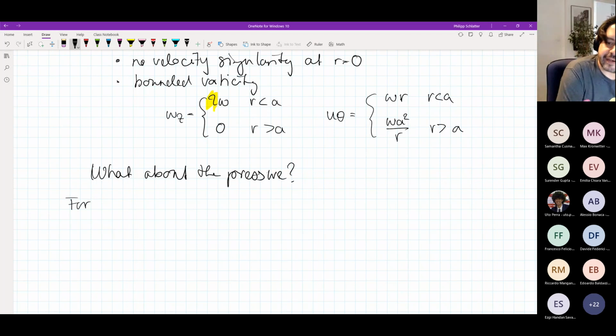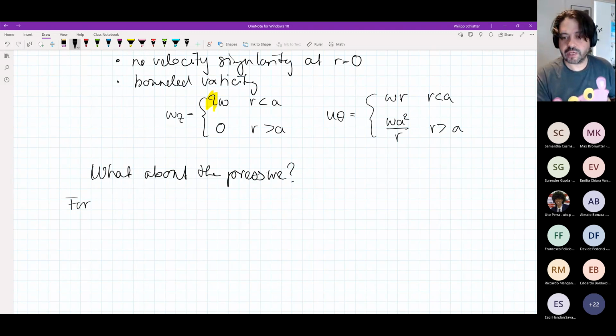Well, let's assume that the flow is inviscid, which we can do. We talked about last time that the vortex solutions are essentially inviscid solutions, or at least they also appear in the inviscid equations, because we started from the vorticity transport equations, but we formulated them in such a way that the viscous terms disappeared. That means the solution for the concentric streamlines, A divided by r plus B times r, is a solution both to the viscous and the inviscid equations. So for inviscid flows,